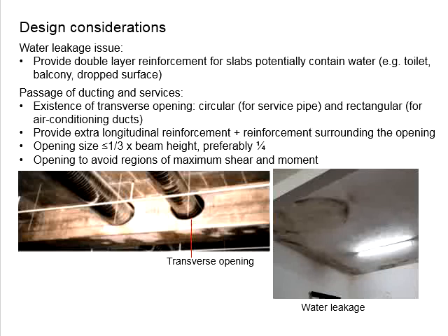If you foresee that there is not sufficient space, let's say you're talking about a PVC pipe of 100 mm, you need to have at least more than 100 mm space underneath the beam but above the ceiling, and then the transverse opening is not necessary. In most cases the space within the ceiling is quite limited.